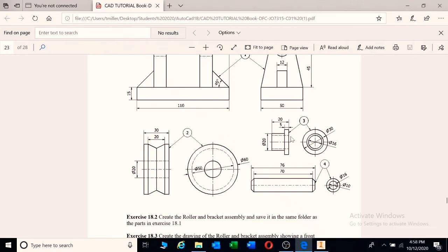So now you will take your first bush and it will go in there, which is 20. And the second bush should always go in on the other side. But before you do that, you need to look at lengths. After your diameter fits, you need to go look at the length. There we have 5, we have 20, so that distance is 15. So putting two bushes in there, we need a distance of 30. So there we have 30, so it will fit in perfectly. So these two parts will turn into one part. So now we have 3 parts.